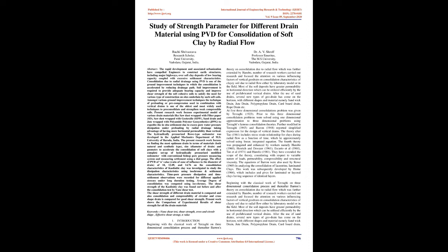Amongst various ground improvement techniques, the technique of preloading or precompression used in combination with vertical drains is one of the oldest and most widely used techniques to preconsolidate and strengthen weak compressible soils.